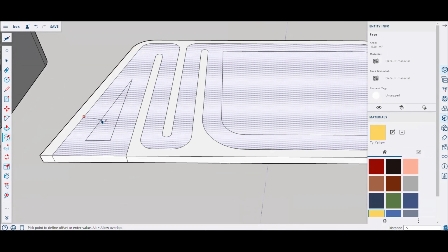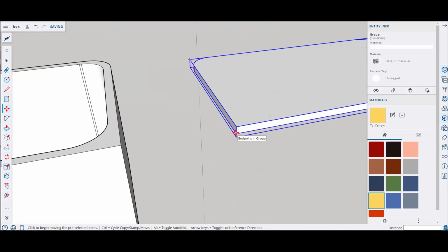Okay, right click, make that into a group, select it, right click, make that into a group. Let's flip this box around and see if it fits, and we'll put the woofer box in as well. All right, rotate. I didn't think I got that right, so I'll do that again. You'll see when you rotate, it clicks into the spot. Press the move tool, just move it out of the way and grab a corner.